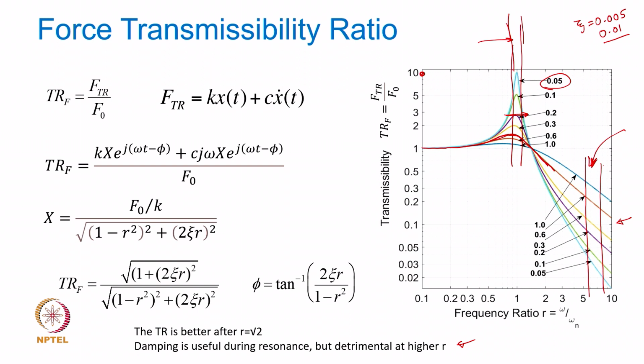So, when you have activated the damper, you avoid resonant conditions, and then when you are past that square root of 2, you deactivate it, so that the lowest damping will be quite useful. So, you can then design your system to have this kind of a hybrid damping or an active damping, that is damping which is activated only when it is required, right. But then of course, it will add to the complexity of your systems and so on. So, as long as you are ready to shell out more money in the design, you can in fact develop your own semi-active kind of a system, where